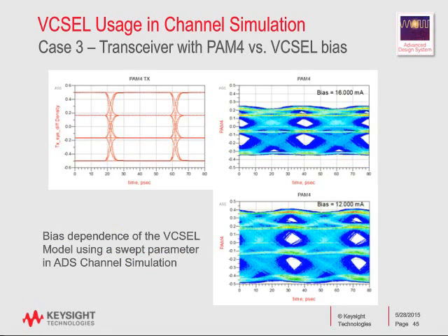So on this diagram here, you'll see on the top left is the transmit waveform, the PAM4 input. And then you'll also see the PAM4 as designed. So this was 16 milliamps. The NRZ signal looked actually pretty good, but the PAM4 signal looks terrible, and you can see that we're definitely a long way up the LI curve here, and there's a lot of nonlinearity occurring at the top end that was not apparent at all in the NRZ signal. But clearly here, where we're trying to look at discrete levels, it's certainly important.